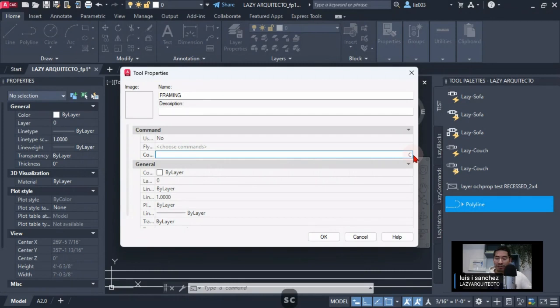So the scale shortcut, of course, would be SC, or you could type scale too. So the scale for this specific example of our friend Duke, usually I'm guessing it would be 2 inches. We'll have framing 2x6, 2x4s, and so on. So I'm going to say 2 for the scale, and press enter, of course. Again, Duke, you can pick your frame exact number, might be 1.5 inches, but I'm picking 2 inches right now for standard size.